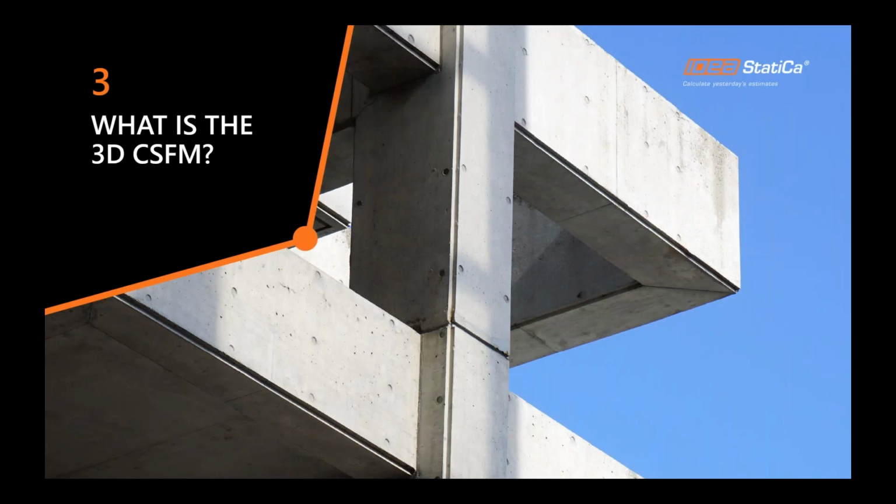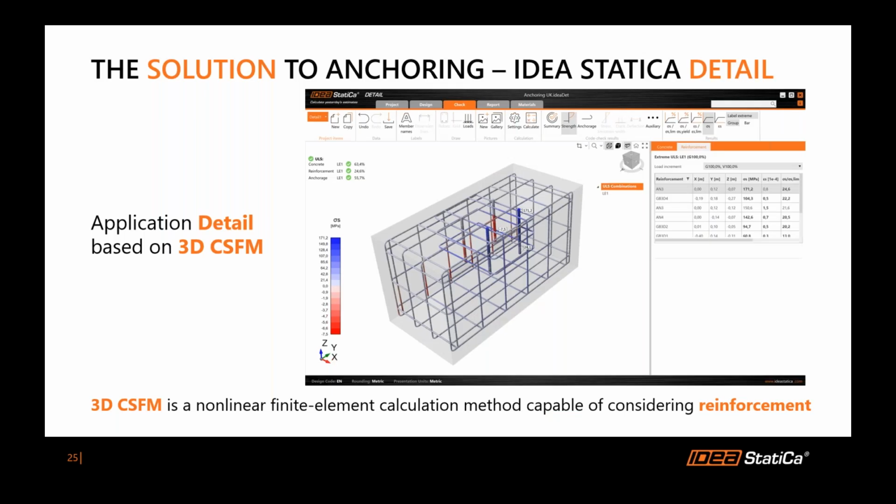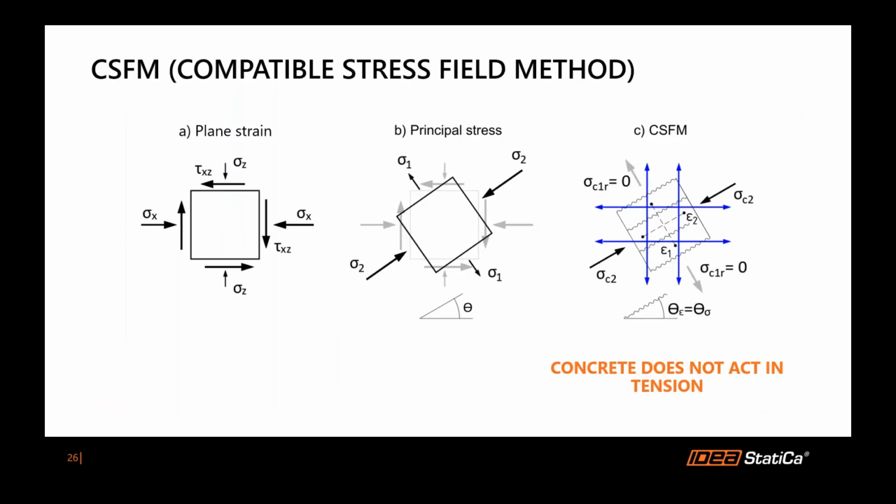And now, I have mentioned the term 3D CSFM many times already. Let's have a quick look at what it is. The method of 3D CSFM is implemented in application IDEA StatiCa Detail, which is not a new application. However, what is new is the 3D model type powered by the 3D CSFM. The method is a nonlinear finite element calculation method capable of considering reinforcement in concrete. The CSFM stands for Compatible Stress Field Method.